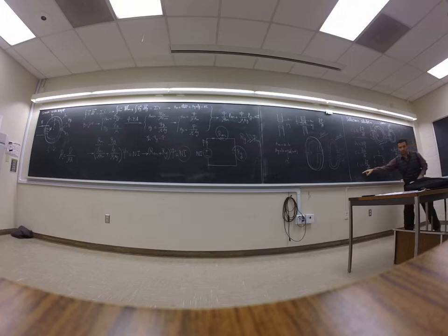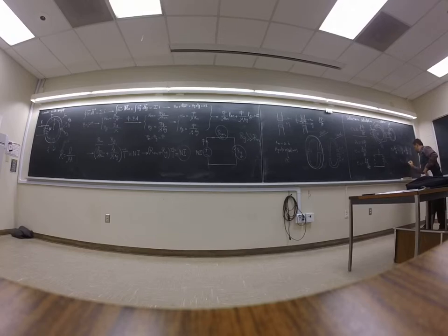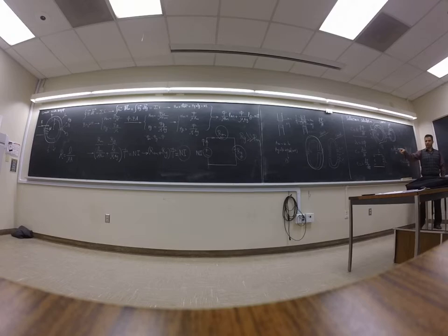And let's bring this equation also in. Also, E was equal to L di over dt, right? This is the Faraday law here, right? E is equal to d lambda over dt. And this is what we know from the electrical circuit, right? For an inductor, E is equal to L di over dt. Compare these two equations. What does it say?